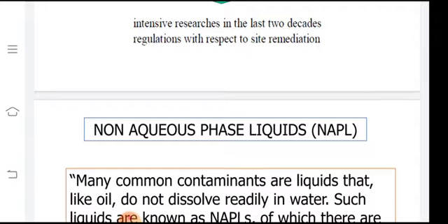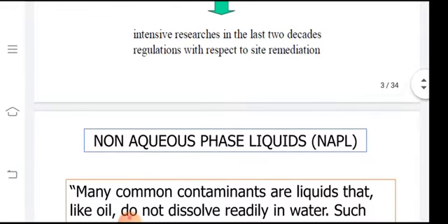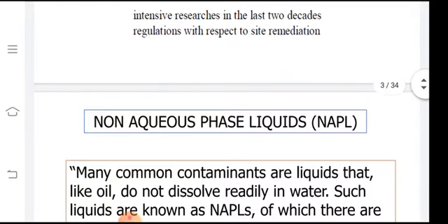After these investigations and determining the behaviors, we need to know how much solute is present in the pores, how much solute has been absorbed by the soil, and how much is going to continue its movement towards groundwaters. All these things need to be investigated. When we use software or a model, or develop a conceptual model for groundwaters, we need sufficient data about these characteristics of the soil, the study area and site characterization.